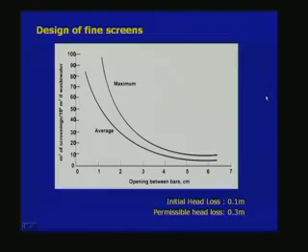That is the reason why, at 1 centimeter width the amount of screenings removed is so much, and if you have 3 centimeters bar spacing, the screenings are very little. So screenings are going to be less if you increase the space between the screens.